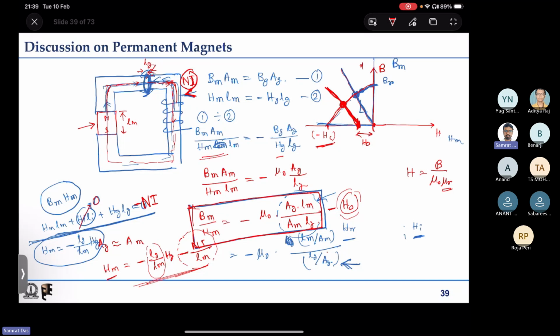No, no, no. By increasing the air gap, it will not. If we do not have any excitation, it cannot become opposite. It will reduce; the slope of this line, whatever line is there, will increase more and more, but it cannot go to the third quadrant.